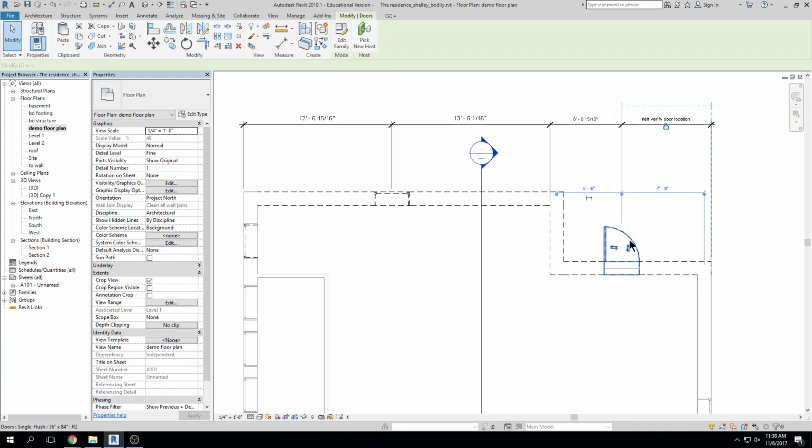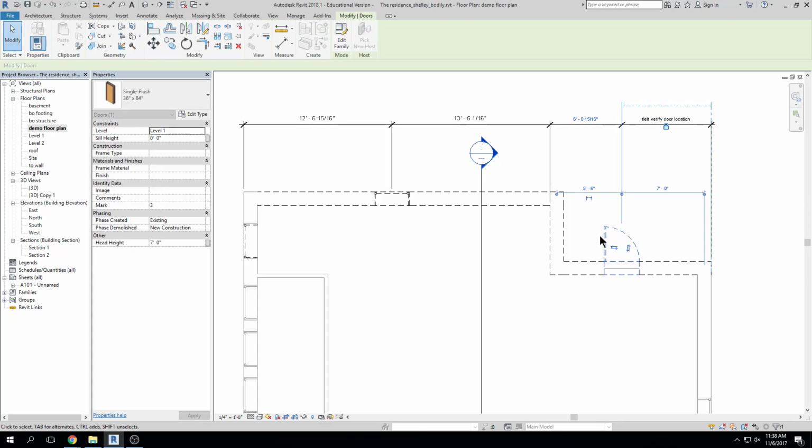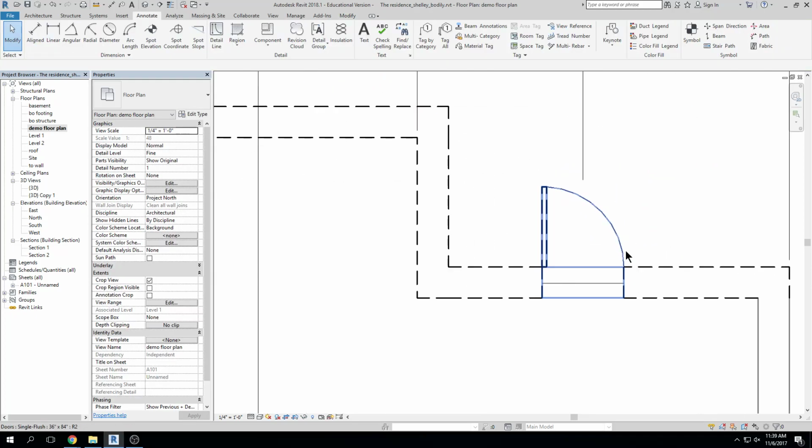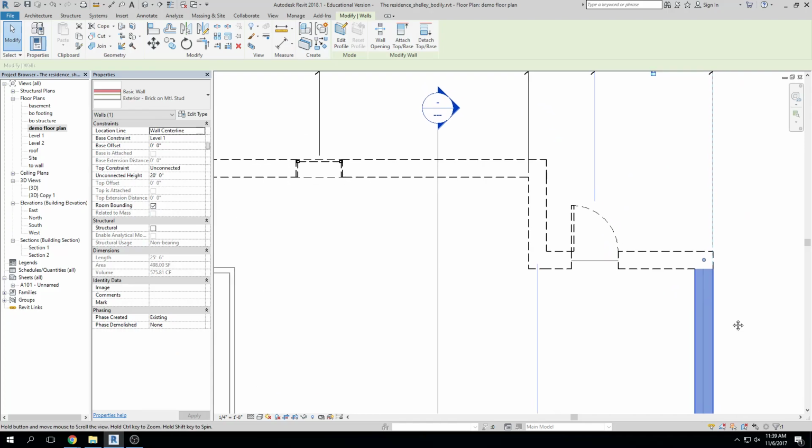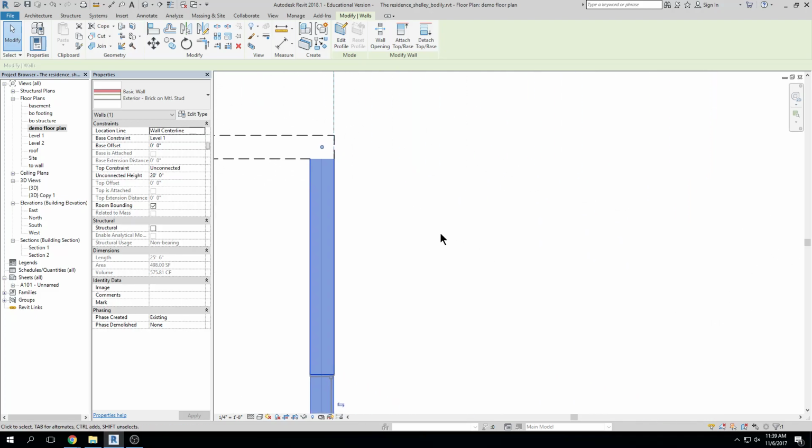And it causes problems because if I go in and I move this door, and it has a constraint on it, let's see if I can... now I can't get the error to work. Let me move this wall. If I decide I want to move that wall, without telling me, Revit just moves the door in this wall. And you think, oh good, I was able to move that wall. But little do you know that the piece is off screen, right?